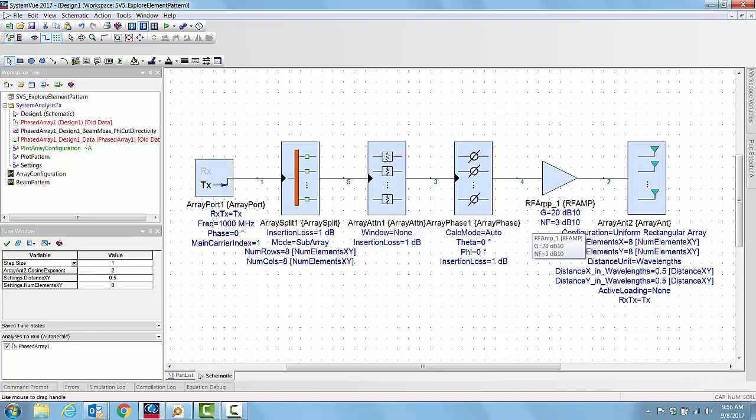That taper will excite each one of these amplifiers differently. When that happens, the output impedance of each of those 64 amplifiers is different. Because of that, they match differently with each of these elements. The elements themselves can have different impedances, and the impedance of each element also depends on the direction of the beam.